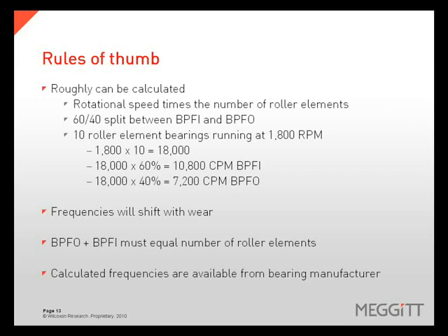The outer race frequency ratio, when added to the inner race frequency ratio, must add up to the total number of roller elements in the bearing. The actual calculated frequencies are available from the bearing manufacturers.